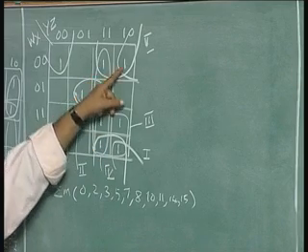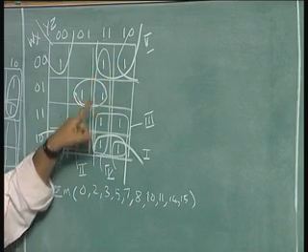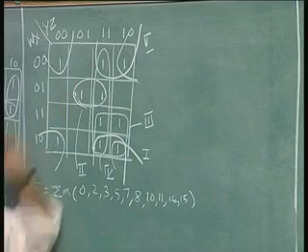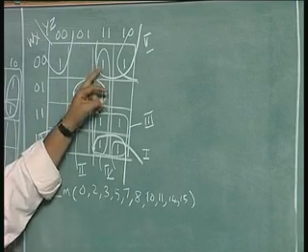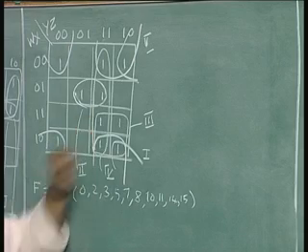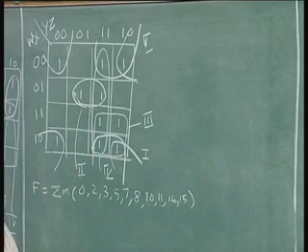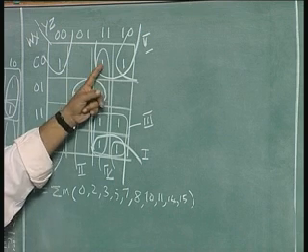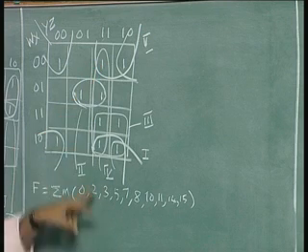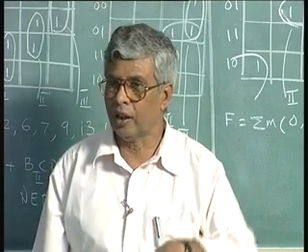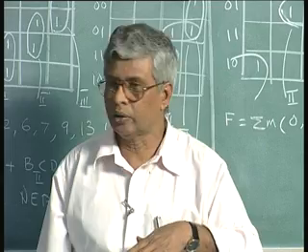In this case, all these have been taken care of except this one, this has been taken care of, this has been taken care of, everything other than this has been taken care of. So, this one can be covered either this way or this way. So, when 4 and 5 are 2 options of covering this minterm represented by this 3, then it is not an essential prime implicant. 4 and 5 are not essential prime implicants, sorry, non-essential prime implicants.